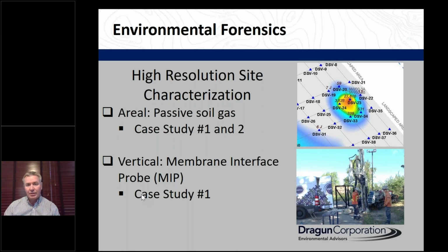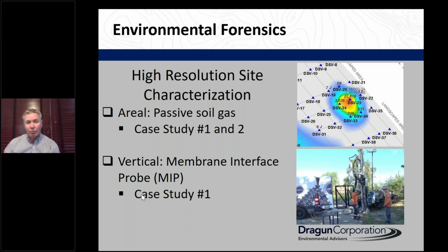Tools like passive soil gas surveys and downhole direct read measurements like membrane interface probe or MIP, laser induced fluorescence or LIF, and a hydraulic profiling tool, HPT, can provide thousands of data points in a single boring without laboratory analysis or time delays. So those tools can help us focus at the area and depth where traditional drilling and sampling are needed, often saving considerable cost.